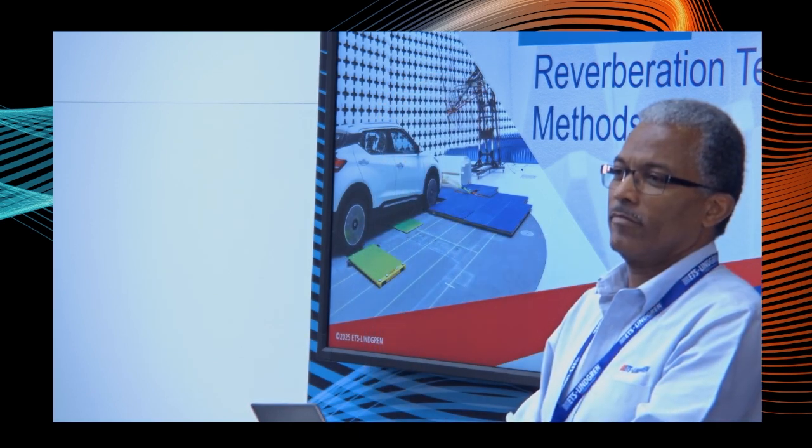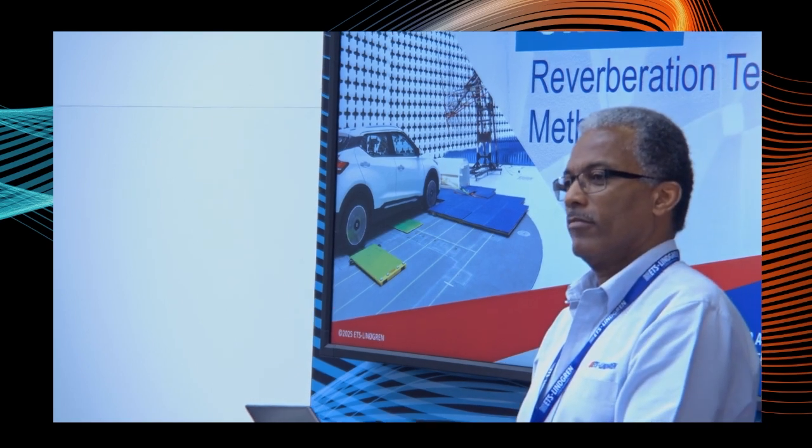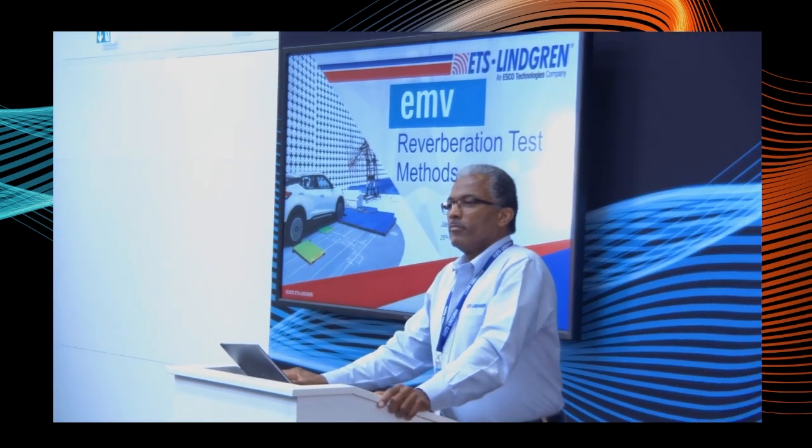A question with the stirrer: which kind of mode can we achieve, in terms of TE or TEM, or TM? In general, I would say the reverb community does not care whether it's TE or TM mode, because usually it's not a perfectly cuboid resonator, and we have many objects in there, the antennas, the stirrer, other tripods for stuff. So we never get these perfect TE or TM modes, and at the end we just want to have a sum and superposition of many modes that are as complex as possible. So we don't care about this.